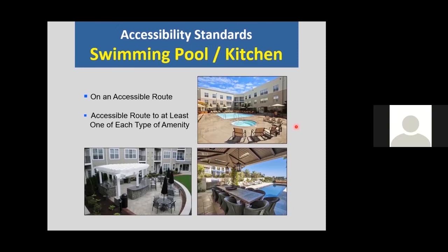These are dwelling units intended to meet fair housing, where the swimming pool is required to be located on an accessible route, but a lift into the pool still is not required. That was something that came from HUD's guidelines and hasn't been picked up yet in private residential projects. We need an accessible route to at least one of each type of recreational facility. If we have 3 tennis courts, we need an accessible route to at least one of those tennis courts.